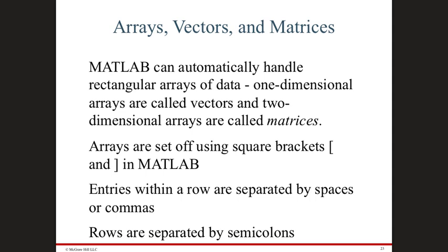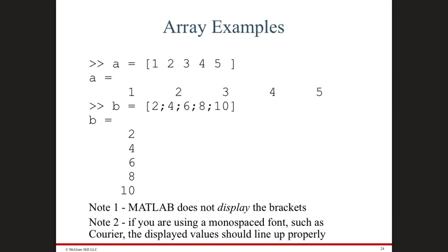In addition to scalars, MATLAB also deals in a nice way, in a seamless way, with vectors and matrices. So again, you can just create a vector or a matrix. You can multiply, divide, subtract, add, raise to the power, whatever you like to do. Whether you want to do this in a matrix operation or something else called an element by element operation. And I will come quickly to that.